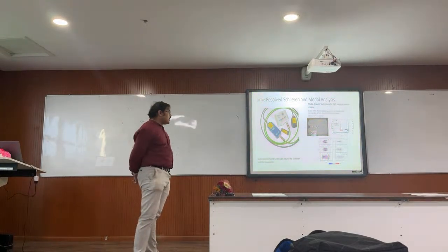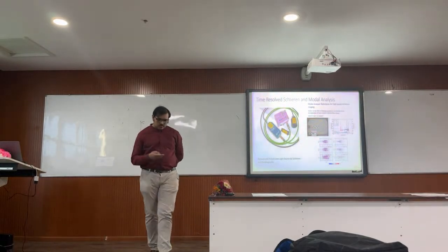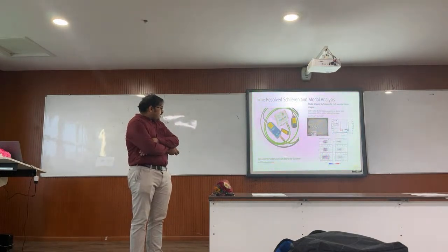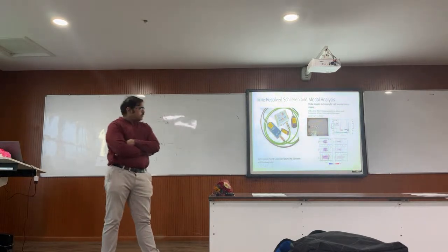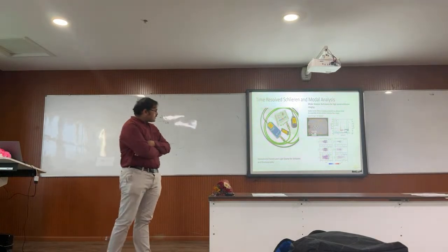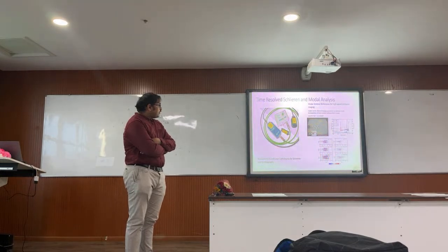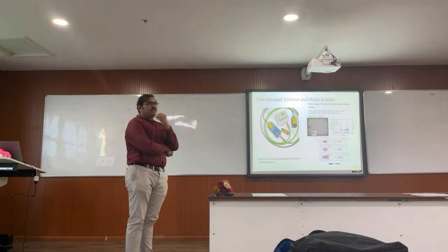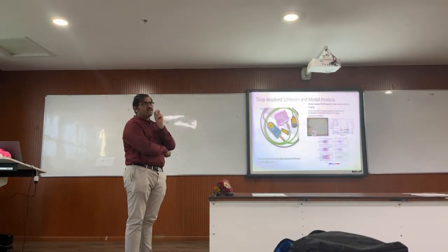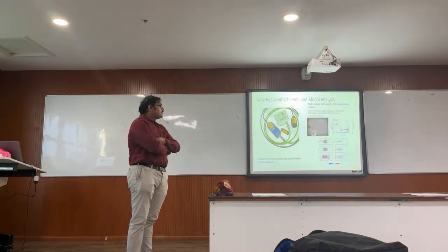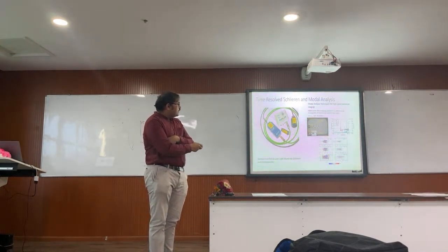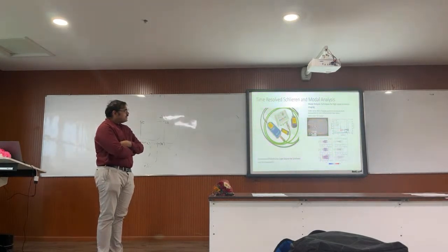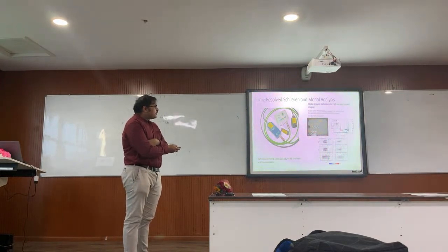So we have to cater to that. We have to see that there is no motion blurring. Therefore, you have to use some special instrument. Here we use a nanosecond pulse laser light source for schlieren and shadow. So it's a non-coherent laser light source, and its pulses can go up to 1 megahertz. But the important thing here is each pulse has a duration of 10 nanoseconds. So we can expect that during those 10 nanoseconds, even though the shock is actually moving very fast, the motion is extremely small, and we have frozen the flow. And if we do this and couple this with a high-speed camera, which can go at 30 kilohertz frame rates, then we can capture very nice images, and these images will be frozen in time.